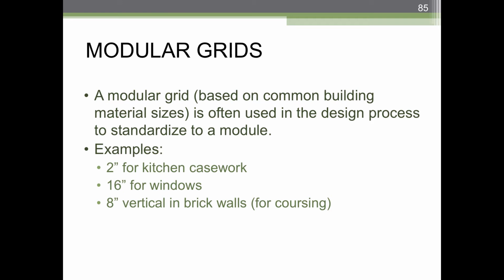What you'll find is that metal door frames that go into brick walls, you have to order them with the brick sizing in there, although the lame thing that you always see is that they just make the head of the door an extra couple of inches thick instead of providing you with a consistent width of the door frame. But that's just another weird pet peeve of mine.